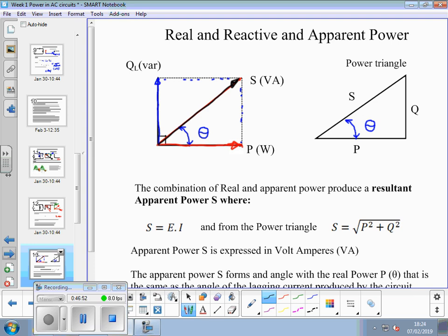You'll always see transformers rated in VA, because you always rate them on the apparent power. They're volt amps because they are naturally an inductive load, and it needs to be considered that they are that.